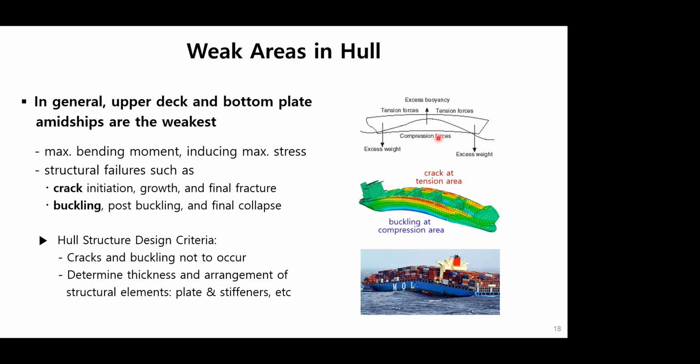At midship, a maximum bending moment is applied, inducing maximum stress, sometimes resulting in structural failure, such as cracks or buckling. Cracks may initiate and grow slowly in time.